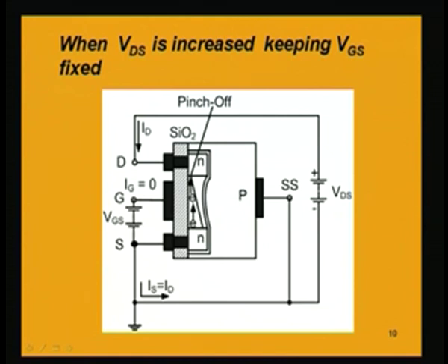But if we go up at any point, if we want to find out what is the voltage between gate and that point, then this is not same as the voltage which is here. So, if we go on towards up, finally reach the drain, then the voltage between gate and that point on the drain will be equal to VGS minus VDS.